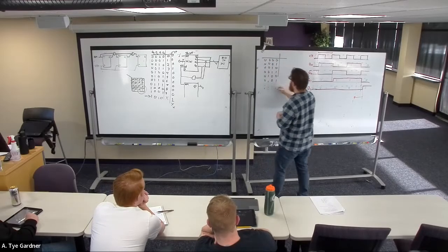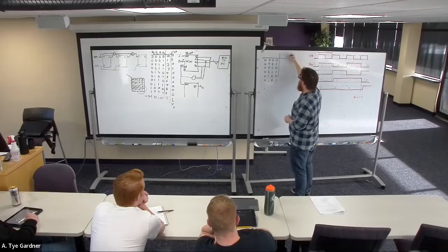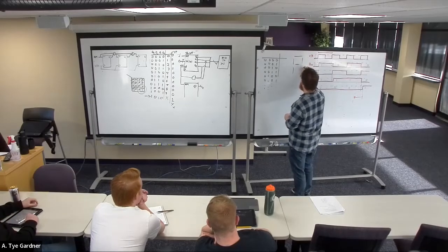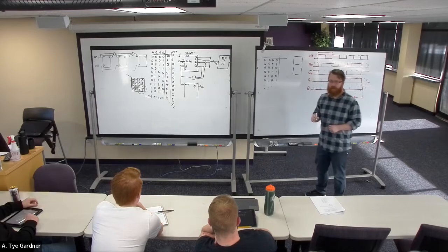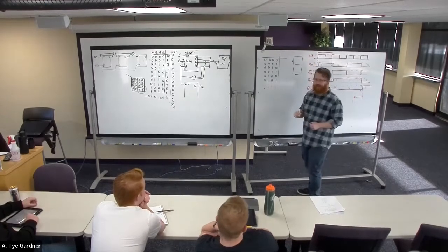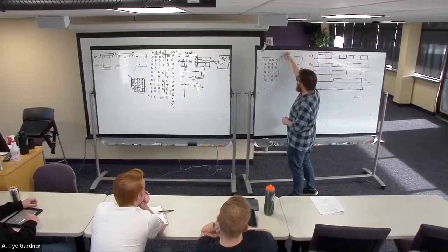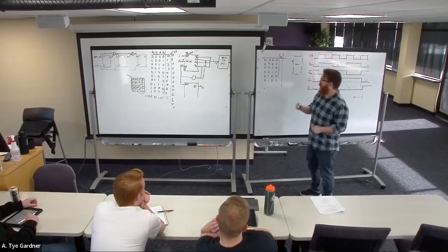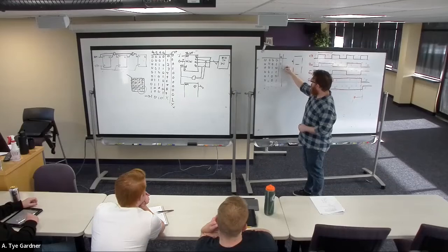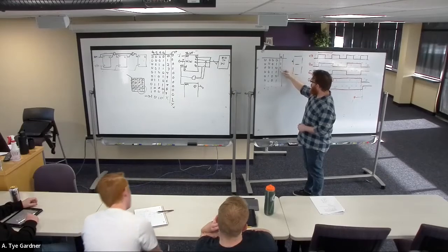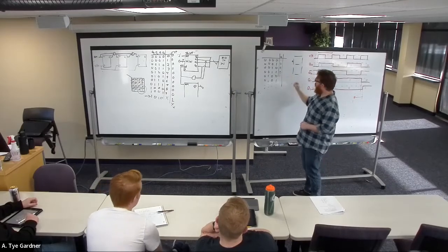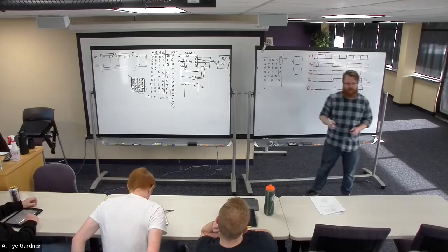And these of course continue on down, right? But the 7-segment display looks like this. And if I call this segment A, then this is my output LED A. And it turns on if I have a 0, doesn't turn on if there's a 1, doesn't turn on if there's a 2, no 3, there is a 4, not 5, and so on.